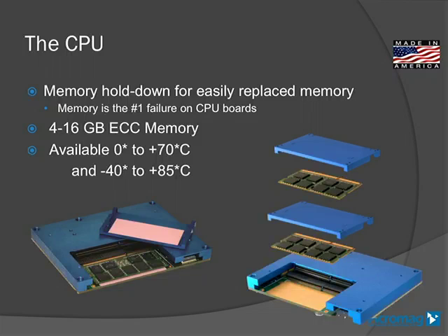Again, aluminum conduction cooling, part of the whole design. This will clamp down through 4 screws underneath the CPU board, holding the first piece in place. The second piece is then inserted into its respective socket, and then there's a top plate, similar to the bottom one, that gets fastened down from 4 screws from above.